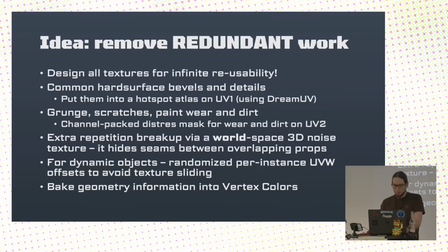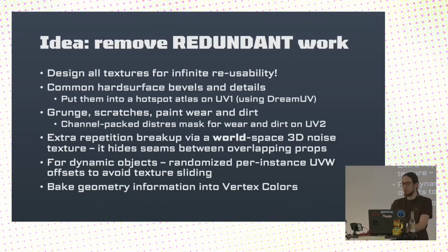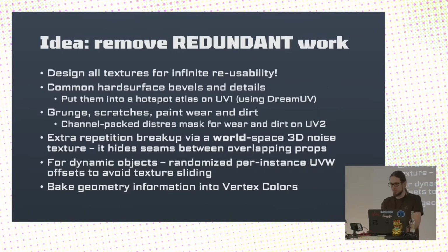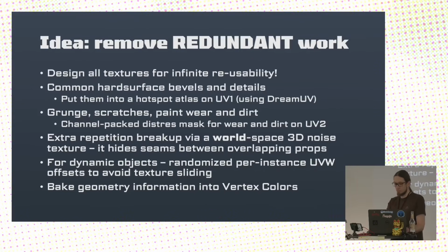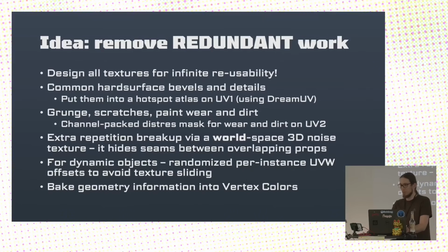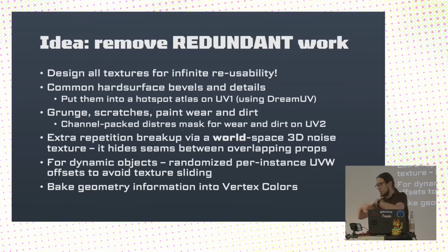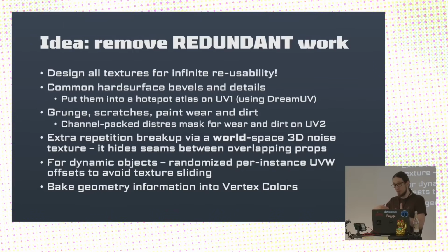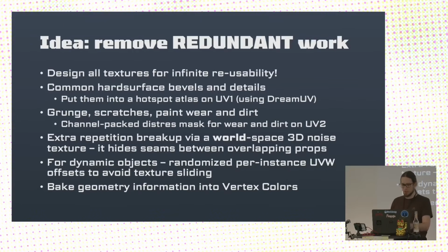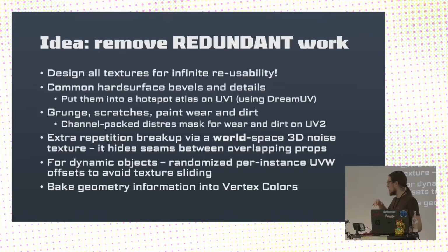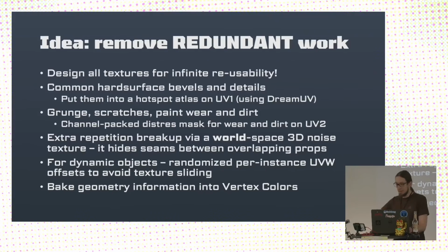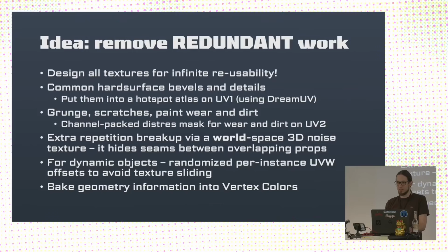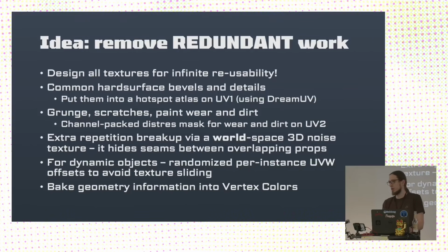One of the very important pieces is baking geometry information into vertex colors, because just having edge bevels mapped with textures is not enough. Then in crevices, you have scratch marks in concave places where there shouldn't be any scratches. But we can bake that information into vertex colors and bring it over, and our shader will say, okay, that's a crevice. There's no scratches there. There's dirt.